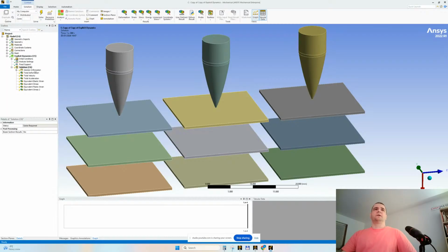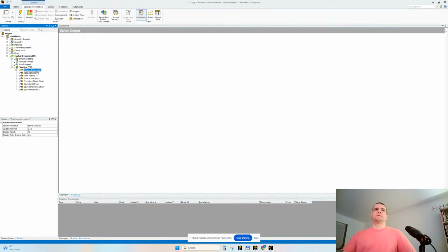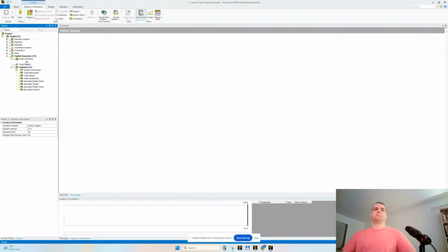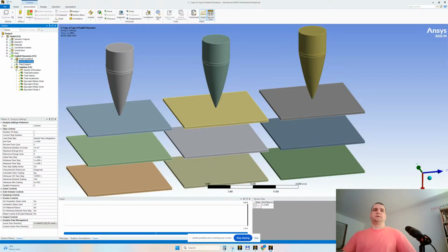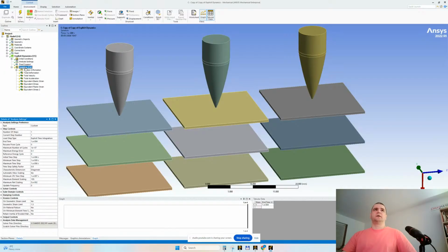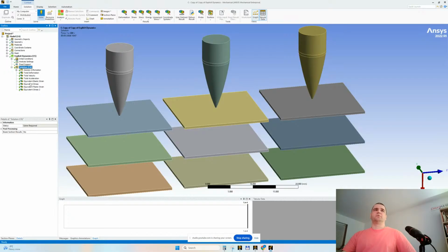solve. So in the last simulation here, it said that it will solve in around 8 minutes or something. Let's see, with mass scaling applied, how long it will take. We'll have the same error, no problem, because we didn't solve the meshing, we didn't correct it, but let's see how long it will take.